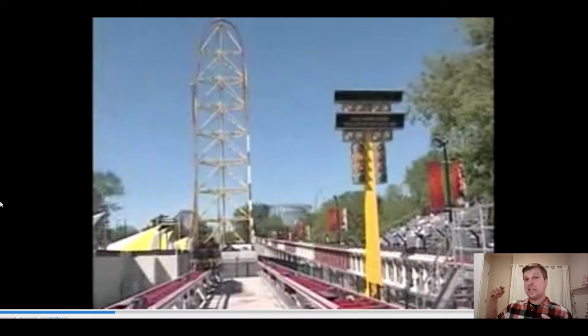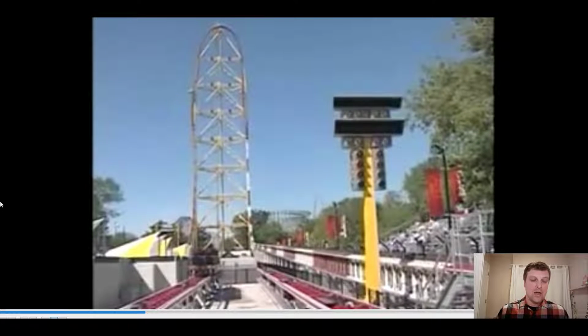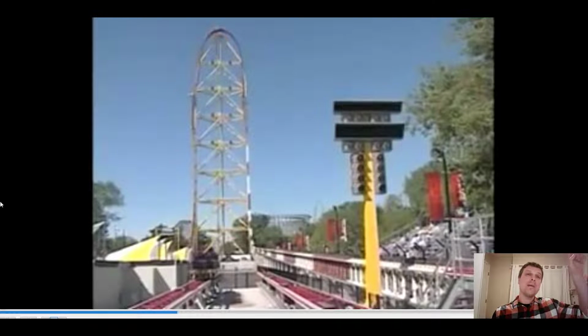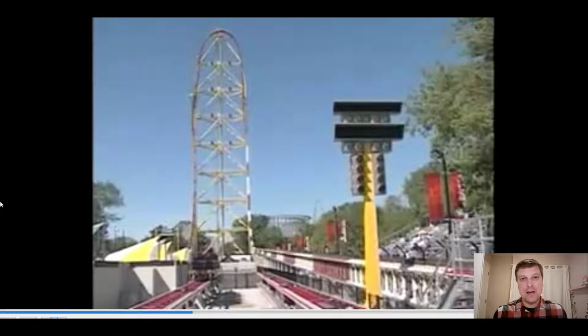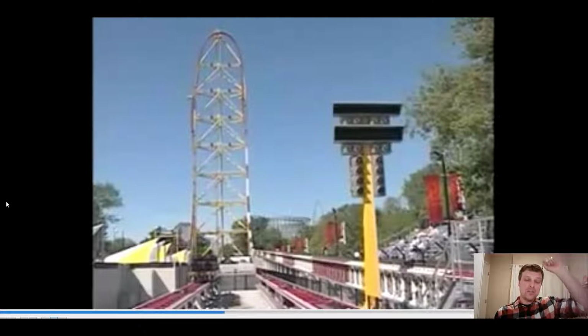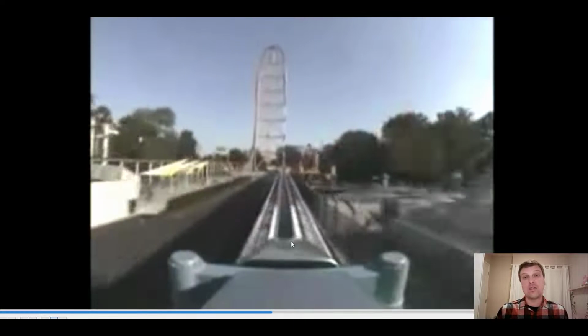The car is basically just accelerated forwards over a pretty short distance, a couple hundred meters or so, and then it turns 90 degrees, goes up in the air, and just barely makes it over the top before falling back down the other side. When they get it just right, the car has just enough energy to just barely get to the top. The key to recognize with this is that the whole energy input for this machine happens during the acceleration phase. It's launched forward by a cable, and then after it turns, it has to make it up over the hill all under its own power. There's no more power supplied to it.